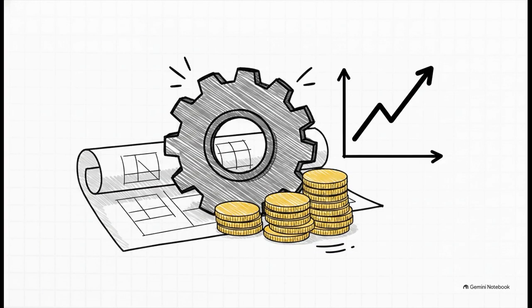Every single decision we just discussed, from datum targets to post-weld machining, has a massive financial consequence. Specifying tight tolerances on an as-welded surface that doesn't actually need it will skyrocket your scrap rates. On the flip side, intelligently utilizing a two-stage tolerance strategy, datum targets, and restrained condition measurement keeps your manufacturing costs grounded while completely guaranteeing your assembly will fit together. Think about it. If you don't understand the exact cost of the tolerance you just specified, can you really afford to put it on the drawing?